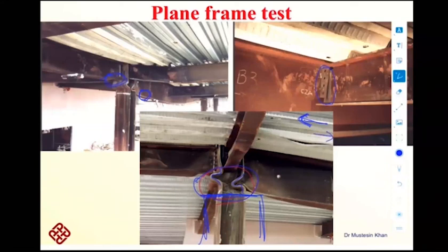And when it was trying to come back, the outside member was at its location, and that is why a kind of tensile force was developed at this connection. The outside member was at room temperature, it was not coming back. Only the inside member which was heated was coming back, and it kind of pulled it. And because of the pull, the bolts failed in this connection.